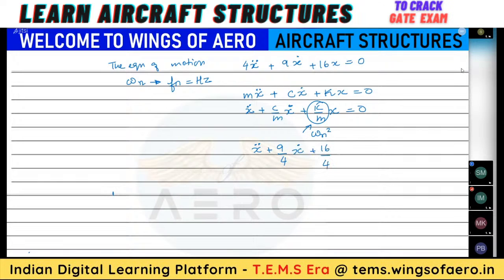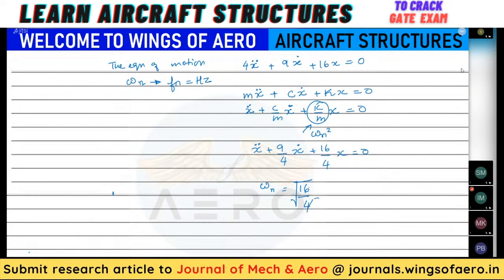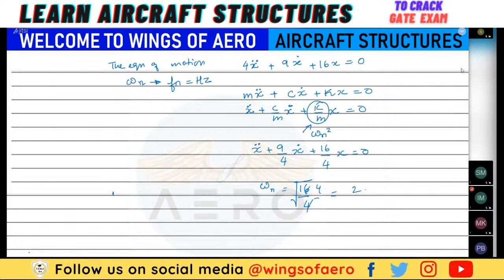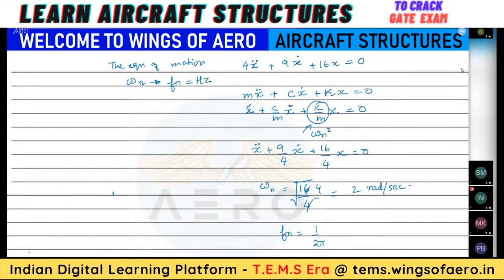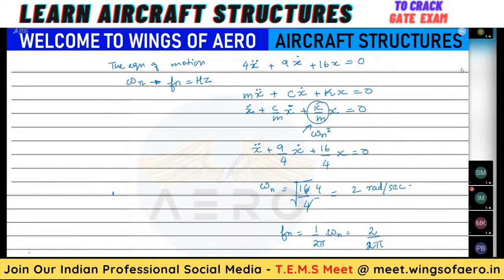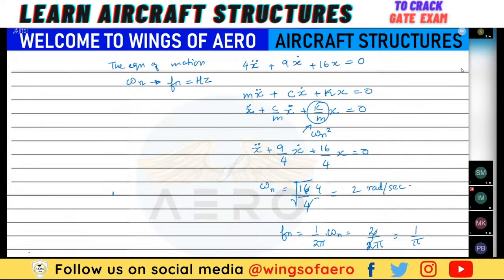So omega n will become root over 16 by 4, isn't it? So your answer becomes 2 radians per second. And if they ask in terms of hertz, so 1 by 2 pi into omega n becomes 2 by twice of pi, can cancel, 1 by pi. So if you substitute the value, or if they have given the options in terms of pi, accordingly you need to find that. Okay.